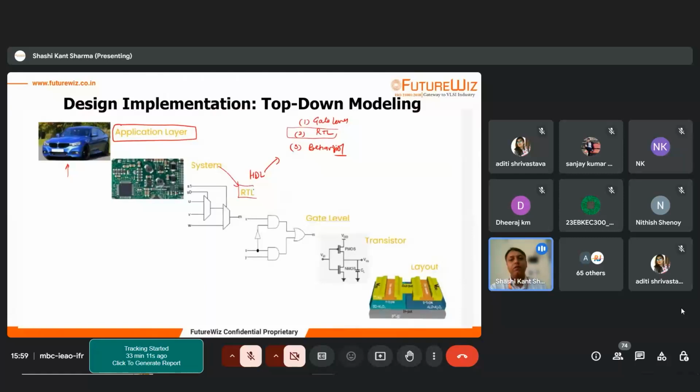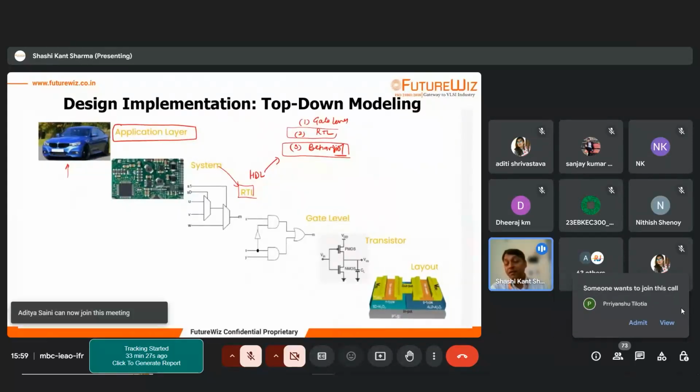That's why mostly we use RTL, because the behavioral modeling style that we choose, which is like a behavioral description of our hardware, may or may not be synthesizable sometimes, right? Okay, then once the RTL design is complete and its verification is completed, as I told you, implementation, design and verification, we go for the gate level.